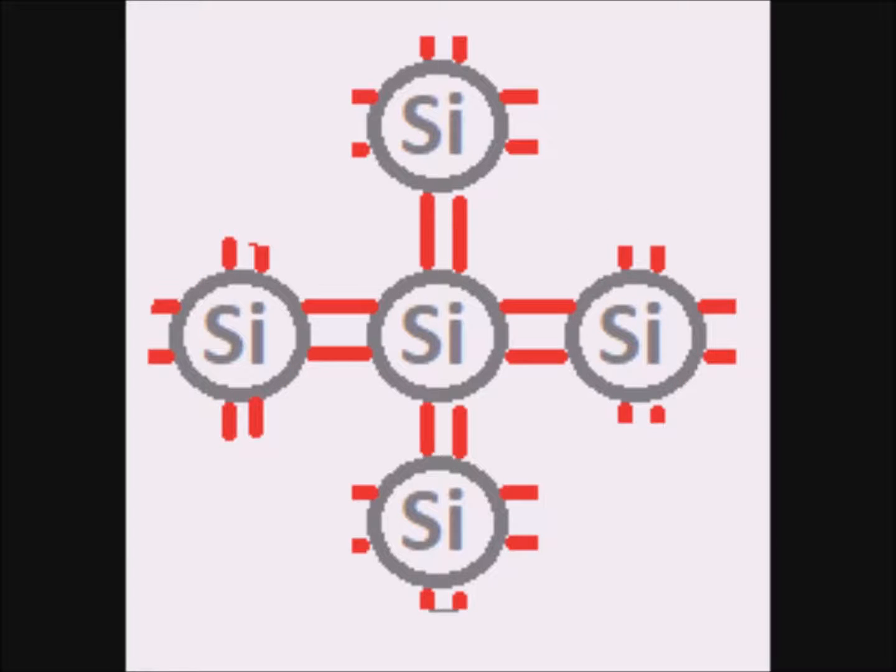A semiconductor is a material which is somewhere between conductors like metals and non-conductors like wood. An example is silicon. The silicon atom has 4 valence electrons, and in a pure silicon crystal, these electrons are employed in bonding with neighboring atoms, so there are no free valence electrons.